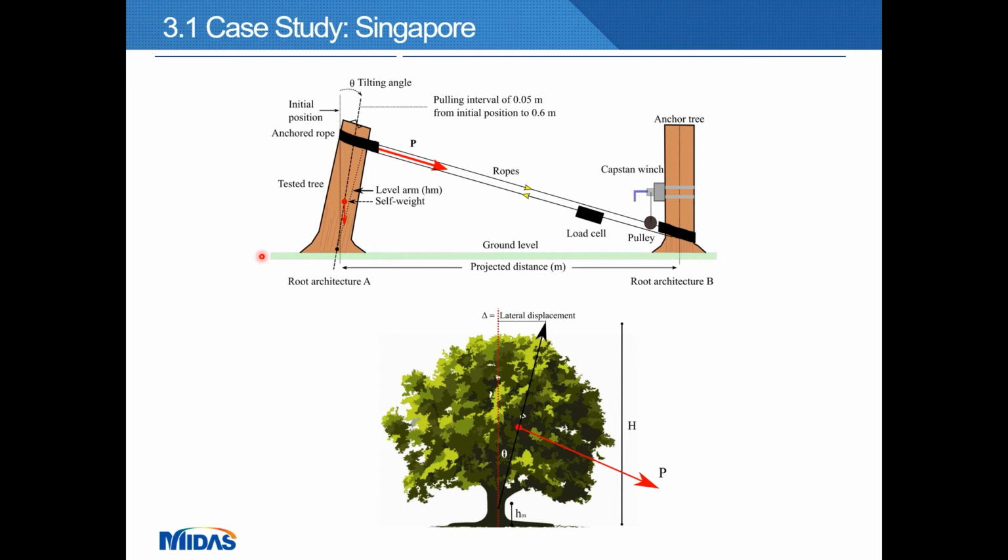These lateral loads were measured using a load cell in line with the pulling rope and an LVDT attached to the tree. So the applied lateral loads, deformations, and geometry of the tree were recorded and used to compute the strains and stresses developed within the trunk, to estimate the overall stiffness of the tree and its anchorage to the ground. A series of 3-point bending tests was also carried out on the branches and the tree in order to characterize the modulus of rupture.